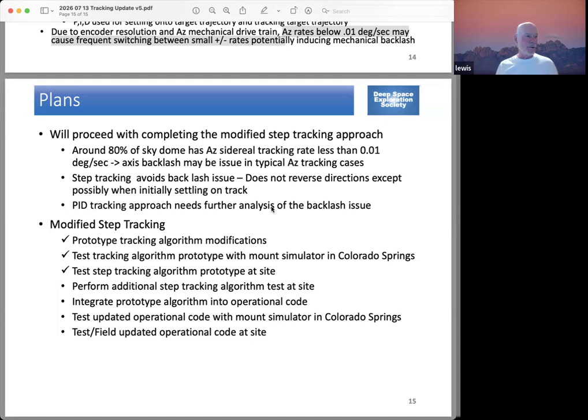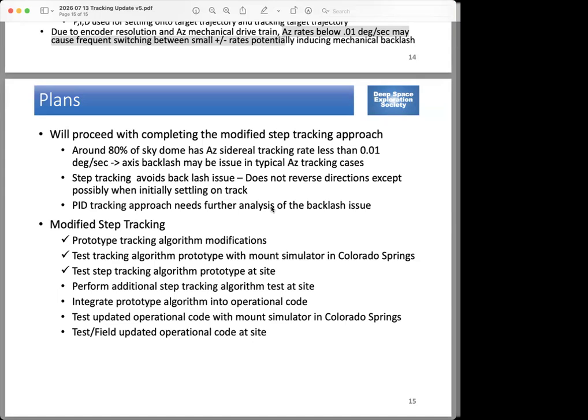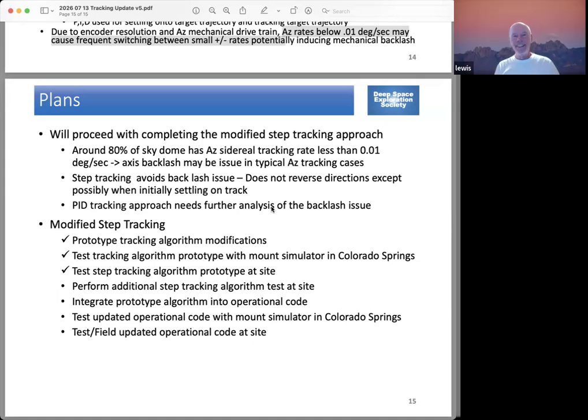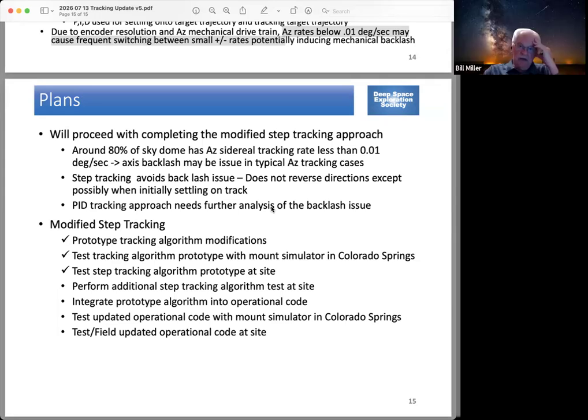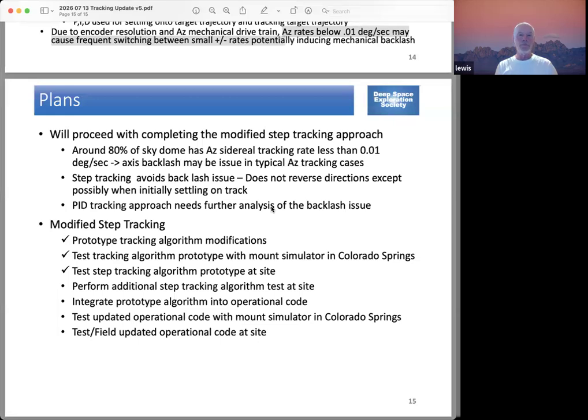Yeah, the sun slewing, like Roger says, is harder than it looks. I think we're going to need the higher resolution tracking or the modified tracking for anything we do with Venus, because the control window is going to be much tighter than it has been in the past, especially if we're at 13 centimeters.